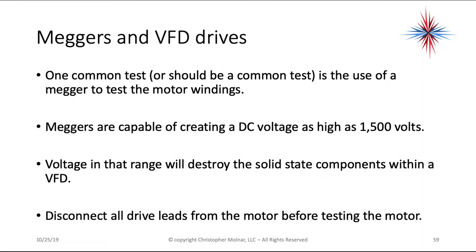There are special notes that need to be talked about when we're using Meggers and VFD drives. One common test, or should be a common test, is the use of a Megger to test the motor windings. Meggers are capable of creating a DC voltage as high as 1500 volts. Voltages in that range will destroy solid-state components within a VFD.